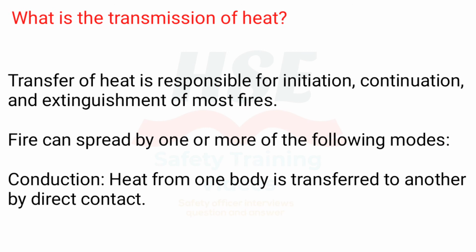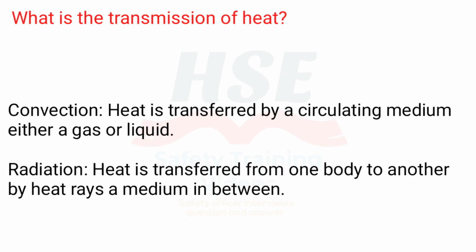What is the transmission of heat? Transfer of heat is responsible for initiation, continuation, and extinguishment of most fires. Fire can spread by one or more of the following modes. Conduction, heat from one body is transferred to another by direct contact. Convection, heat is transferred by a circulating medium, either a gas or liquid. Radiation, heat is transferred from one body to another by heat rays, with no medium in between.